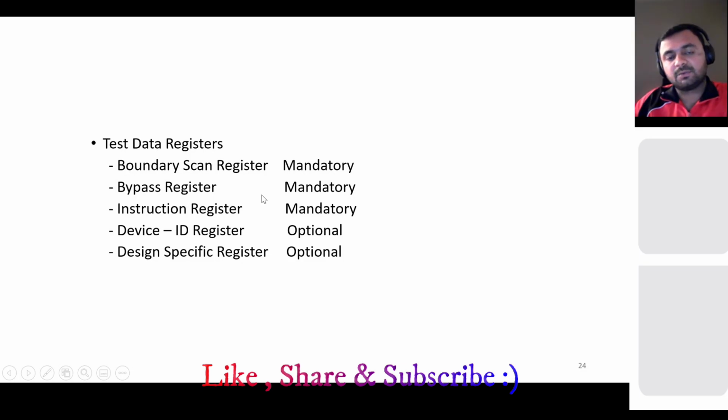Bypass register is nothing but, suppose on a board you have 10 different ICs as we discussed, and you want to bypass the first 2 ICs and test only the third IC, or you bypass the first 5 ICs and you want to test the 6th IC. So there it is used. To bypass the first 2 ICs, you can just use the instruction and you bypass that IC. If there is muxing logic there, it will bypass the first 2 and go to the third, or basically to bypass any of them, this is used. So that's why it's mandatory.